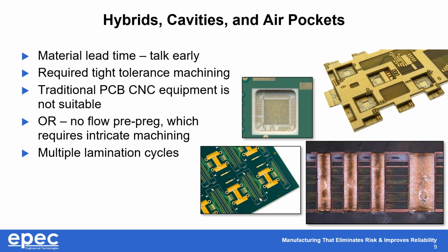And so if you were to try to put the whole stack up into one lamination cycle, you would have to get to a temperature and a time that would do damage to some of the other parts of the board. So it creates 2 lamination cycles, which creates additional time for us as a fabricator.